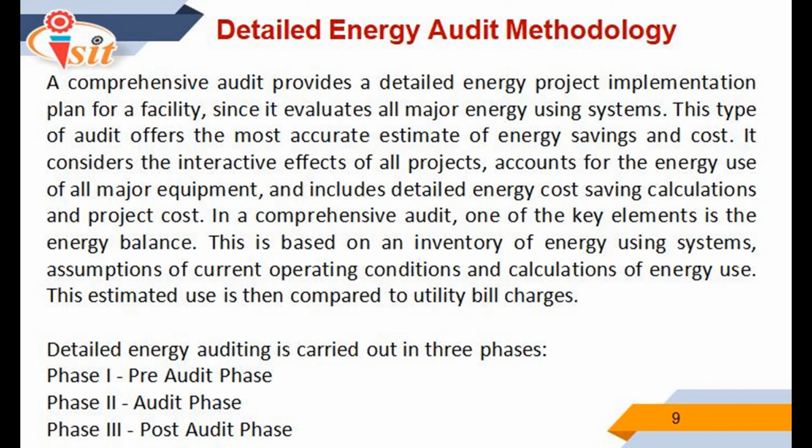The comprehensive audit has one key element: the energy balance. This is based on the inventory of energy using systems, assumptions of current operating conditions and calculations of energy use. This estimated use is then compared with the utility bill charges.